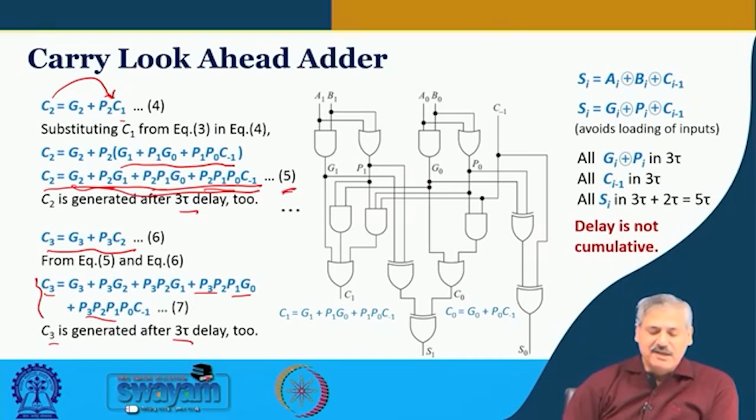Now, one needs to be careful about how many gates it is getting connected to, the fan-in and fan-out issues. So, as long as that is not violated, it is able to provide as much current or sink current, so there is no issue. Okay. But that is something for which we cannot indefinitely extend it.